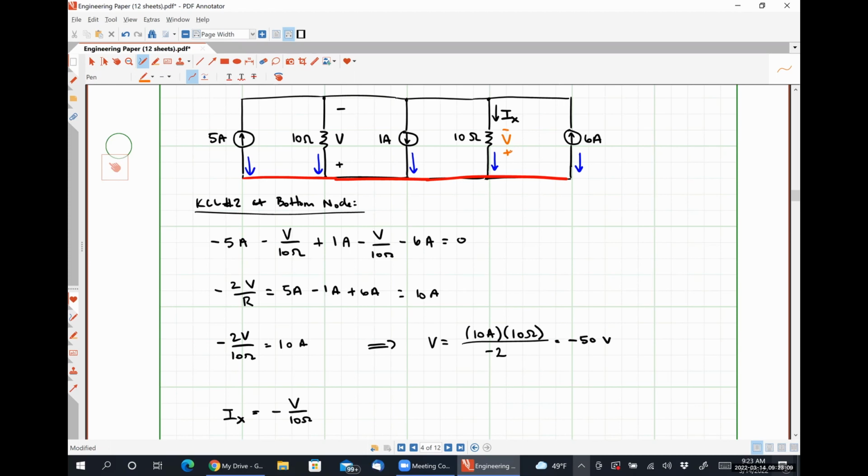But if we scratched this out and put plus Ix right here, when we substituted this relationship in, we would get literally the exact same results. It's all about observing that since the current is flowing into the negative polarity terminal, our Ohm's law relationship needs to have a negative sign associated with it.